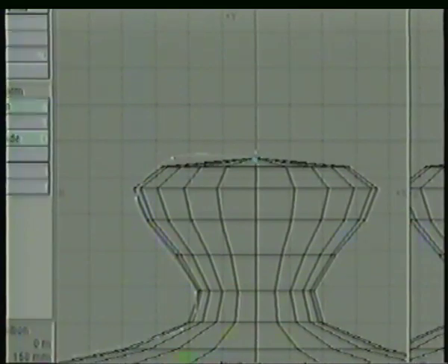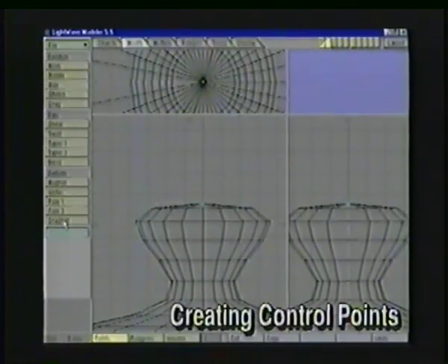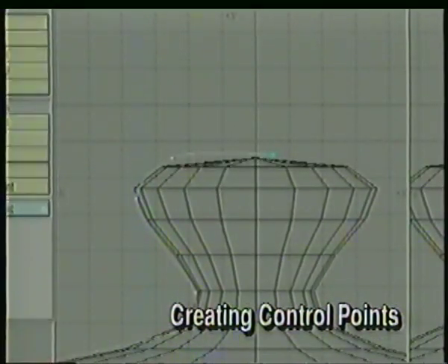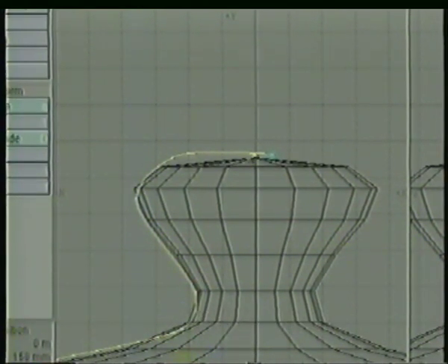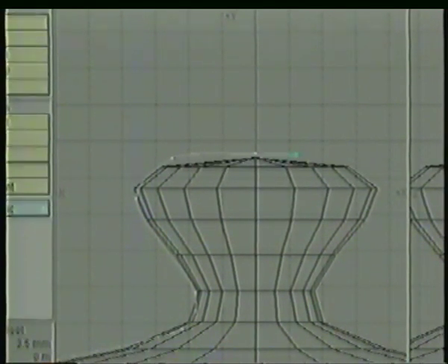We're going to pull this point with the drag tool over to the side. I'll deselect that point. I'll make sure my polygon is selected because I'm going to add a point again. This time I'm going to add it back in the center where the original point was. What I've done is extended my spline farther than I'm ever going to want to lathe it. So I'm going to select that point and pull it even farther with the move tool or the drag tool.